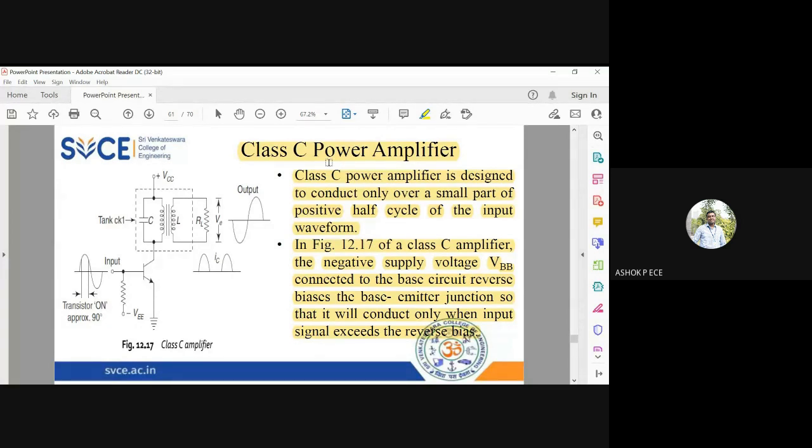Okay, so efficiency and distortion should actually be inversely proportional, but they are directly proportional and you cannot do anything about it. If you can compromise on distortion, you will have very high efficiency. But if you want very good signal quality, then you have to use a Class A amplifier only, because only in a Class A amplifier is my distortion going to be completely zero. So please understand how these amplifiers are categorized and how they are going to be used in real-time applications.